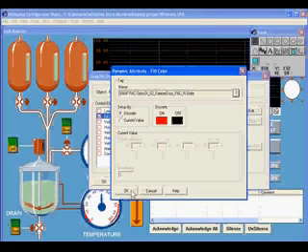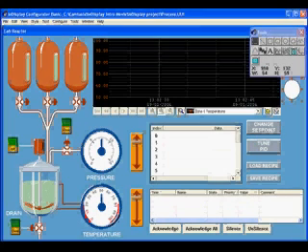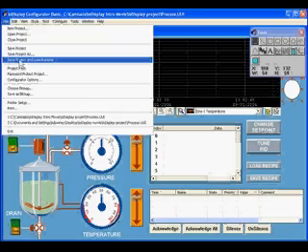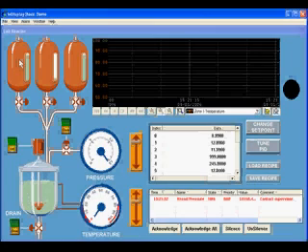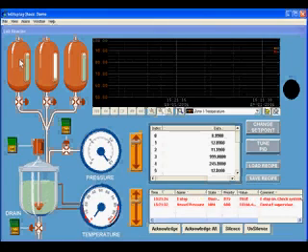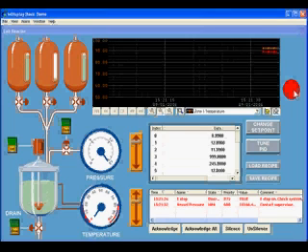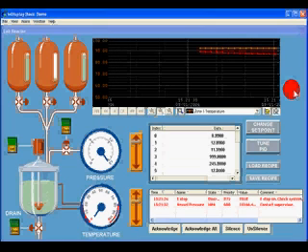Let's run everything and see how it all works. Choose File, Save Project, and Load Runtime. We're now in ioDisplay Runtime. If I flip the switch on my load panel, you'll notice that the color of the button that we just created changes.